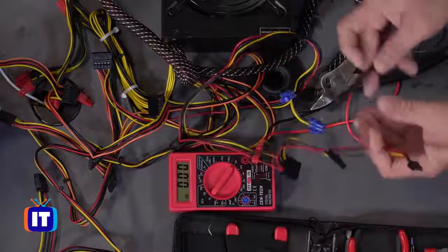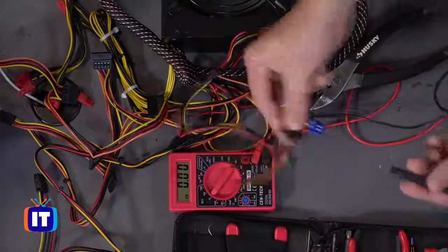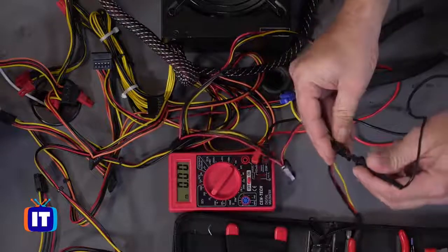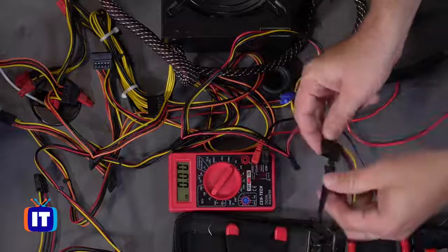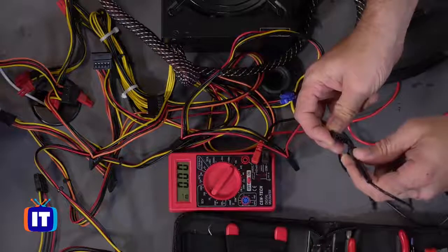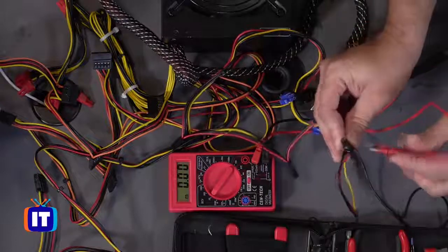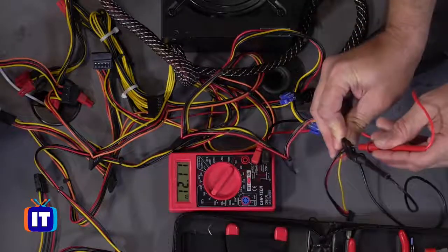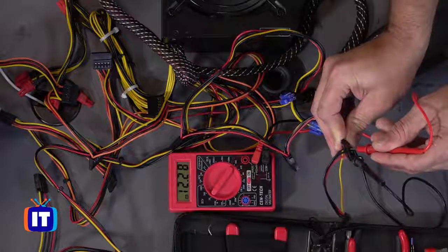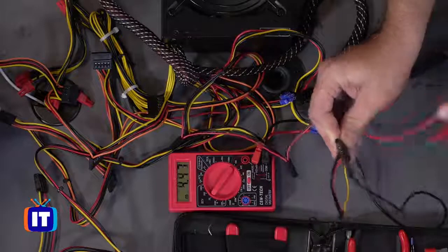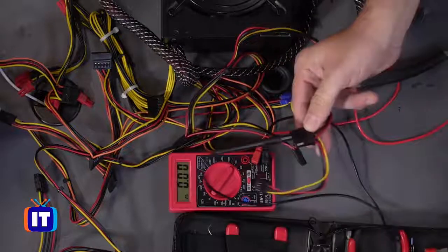And this one's actually a little easier to test out, because you can take your negative, your black, which is your ground here. We can test the same thing, putting the black probe into the ground, and then we can test, for instance, the yellow wire here, and you'll notice the same thing: we get our 12 volts. So we can see from two different rails that we're getting 12 volts off of each rail. I'm going to move this over a little bit so we don't arc out here,